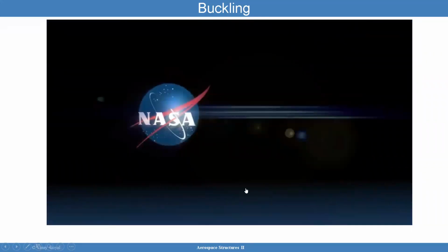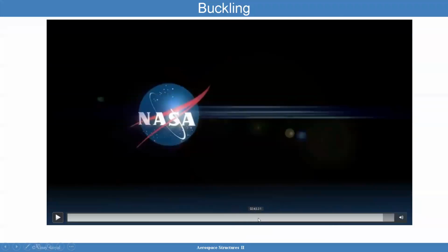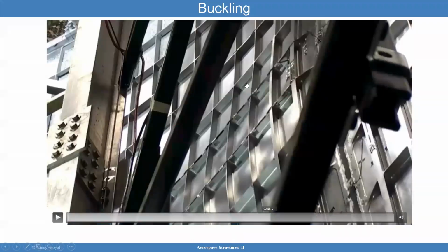Okay, so what you guys saw about here, these are orthogrid stiffened shell structures. So this orthogrid provides additional support to the skin wall. Without this, it will buckle much faster. When I talk about pocket buckling, what I'm talking about is buckling of these pockets here that are surrounded by these ribs that you see.